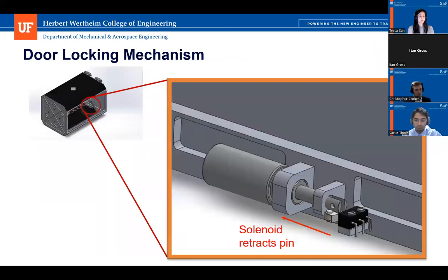The door locking mechanism relies on a linear pull solenoid attached to the inside of the front plate. When armed, as seen in the image, the shaft of the solenoid is fitted through a hole in the tab fitted to the door. The solenoid will retract itself when a current is applied, thus beginning the dispensing process of the CubeSat. A limit switch, seen in black, is positioned opposite the solenoid such that the status of the door opening can be monitored by onboard systems.